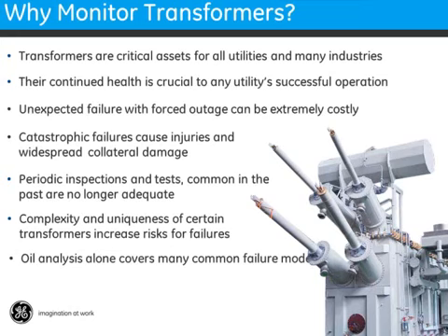Their failure can have financial cost, environmental cost, safety implications, and even political ramifications. We all see examples every year where a transformer failure gets reported in the global media, especially if it brings down part of a grid. So why monitor transformers? Well, very simply stated, any transformer which does not feature some type of continuous online monitoring as part of its standard protection scheme is at risk of an unexpected failure. While monitoring will not prevent a failure, it will forewarn of that failure.